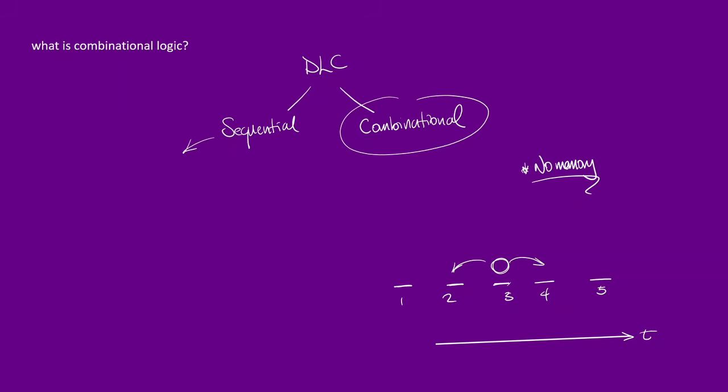When you get to sequential circuits, you see that devices under this category have what you call a memory. They can latch onto memory, they can latch onto current states, and whatever it is now definitely has a role to play in the states to come. But combinational logic is independent, meaning that whatever state you're in is not affected by what was before it, and is not going to affect the state coming up next.